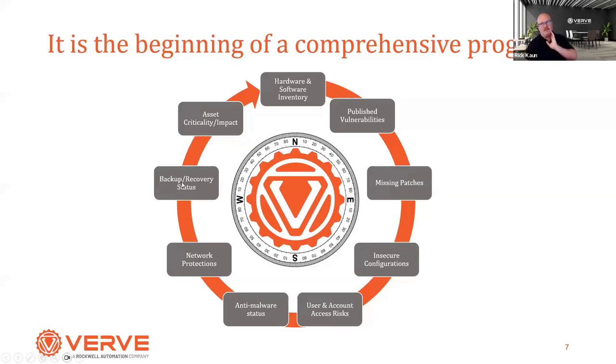In the world of OT, even if there is an intruder, it's interesting. IT would want to track and trace and grab forensics. OT wants to nuke them and get back to good. So that's why we have a very rudimentary but powerful fail, get back to last known good, get back up and running. But it all hinges upon this. We're not going to have the same level of backup and restoration practice with redundant systems or supporting systems like file servers as we will with critical safety systems and HMIs, et cetera.